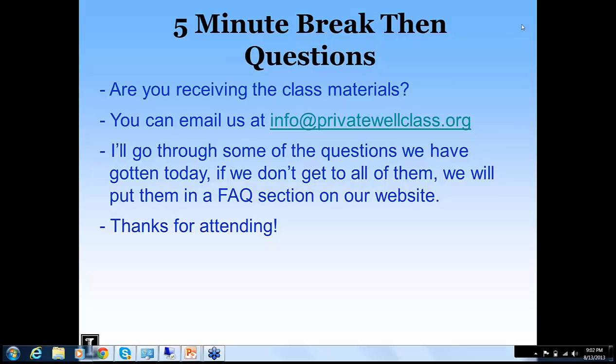But it really depends on your situation. There's a lot of things you need to do to protect your well. You need to be aware of where your well sits on the landscape. Is it prone to flooding or other risks? Is the wellhead actually properly protected as far as the type of cap you have on and what you store near your well, all those sorts of things.